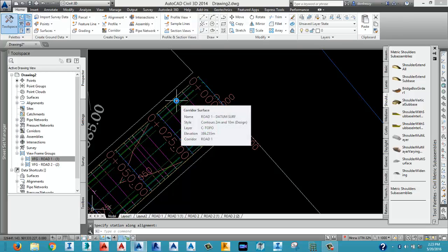Let me just give you some info now. Whenever you are doing a design, once you want to get into your earthworks computation, it's always advisable you have 2 copies of the same design. You finish your design, you want to produce one for plan and profile production, and you need one for your other computations. So once you finish, you save, then you save another copy as cross sections and earthworks computation.